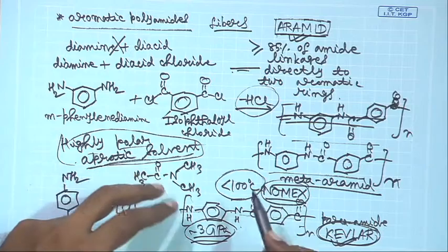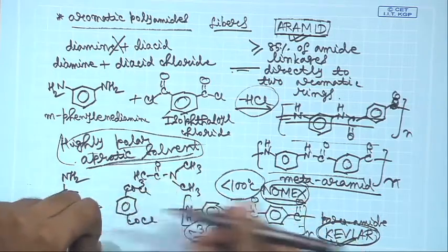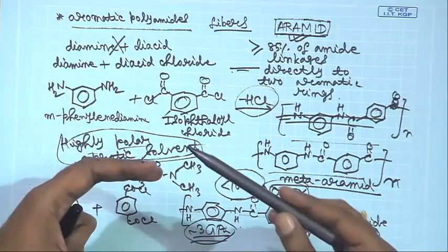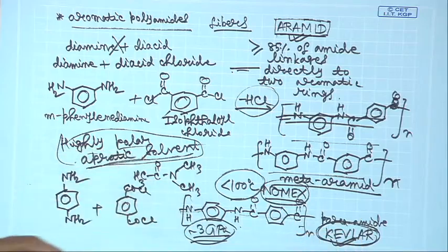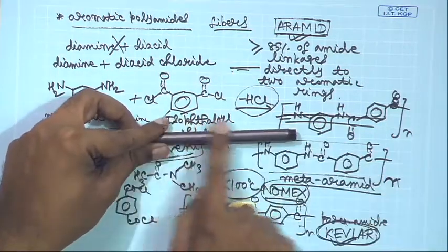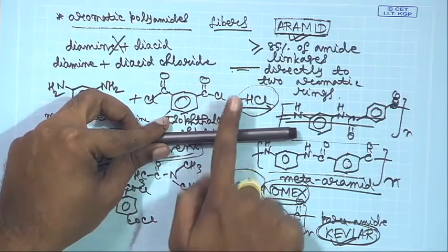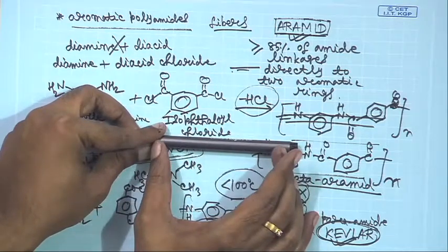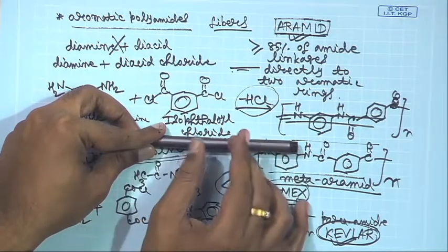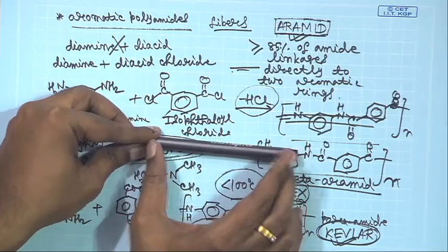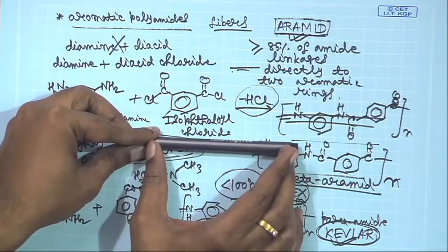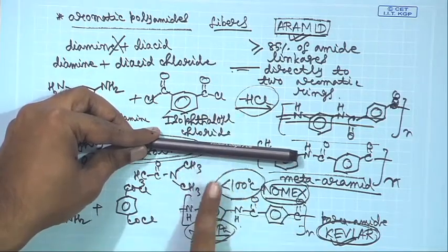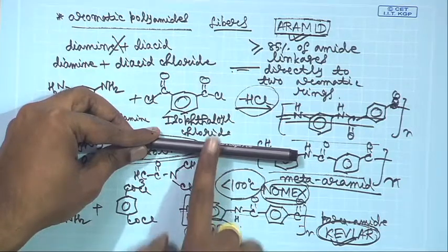All these things will make the material highly anisotropic, because along the length of the fibers, since they are all oriented along the length, you will have enormous tensile strength. So this is the length of the fiber. Along the transverse direction you will have the hydrogen bonding interactions, which are definitely weaker, because along this length you have the polymer chain itself, with covalent bonds between the molecular units, the chain extended along this length. So the tensile strength is quite high, but in the transverse direction, you will have hydrogen bonding interactions, and so that is weaker.